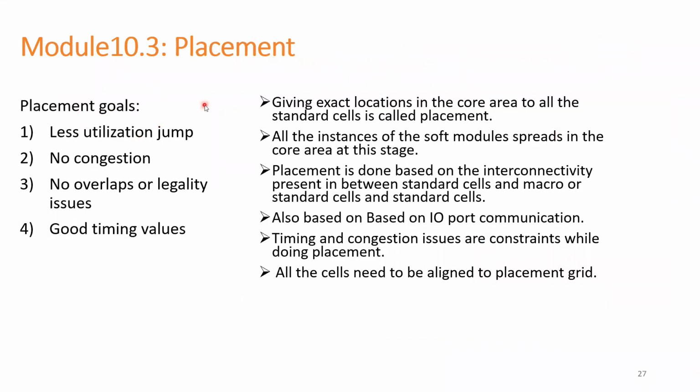So placement goals. These are all the placement goals. There should be less utilization jump. Let's say for optimizing the timing, the tool should not add more buffers or any other cells for optimization. So we should have good control over the cell usage shoot up, and there should not be any congestion post placement. So this is also one of the goals.